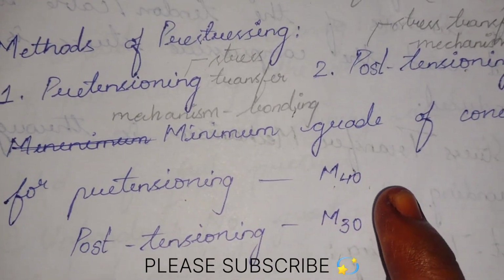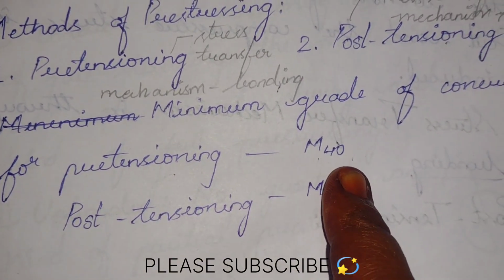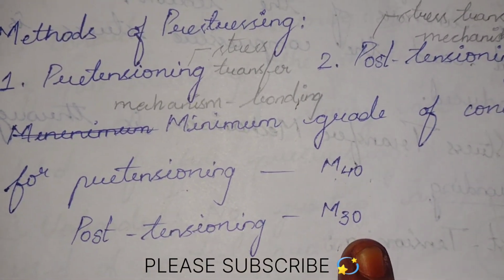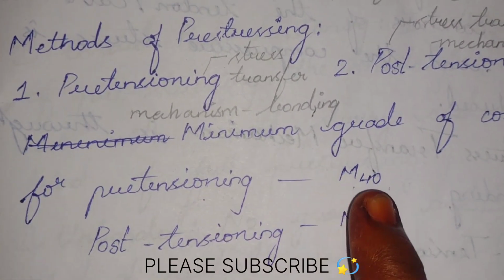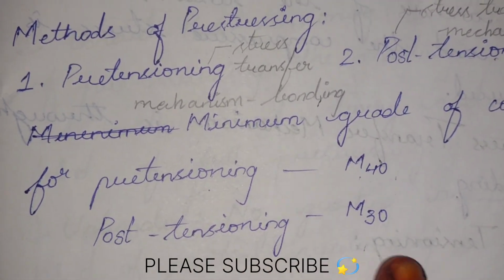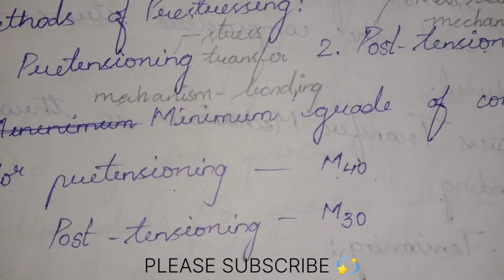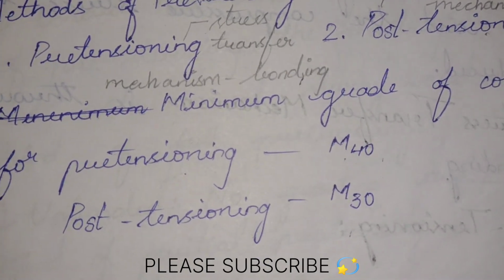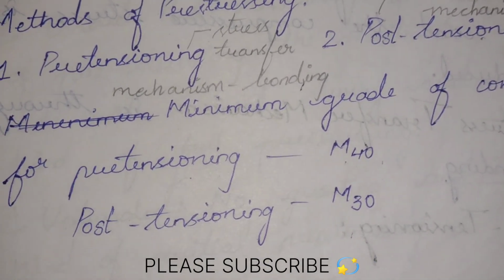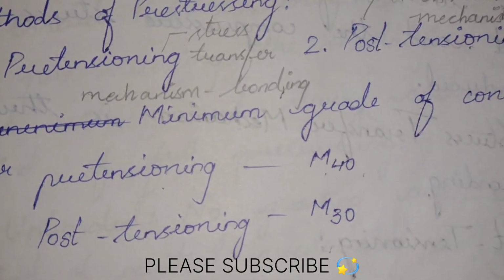As per the codal provisions, the minimum grade of concrete for pre-tensioning is M40, for post-tensioning is M30. Remember, the minimum grade of concrete for pre-tensioning is M40, for post-tensioning is M30. This is a very important point that can be asked in any sort of competitive exam. Even in any interviews, this would be the most general question that would be asked in prestressing.